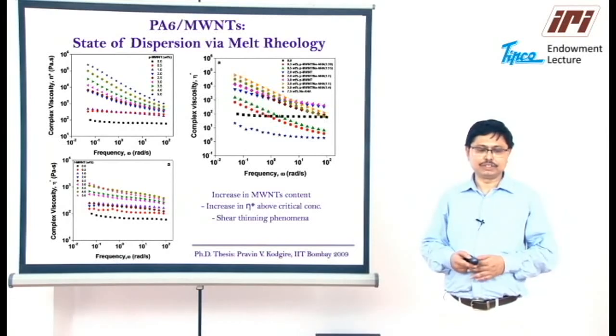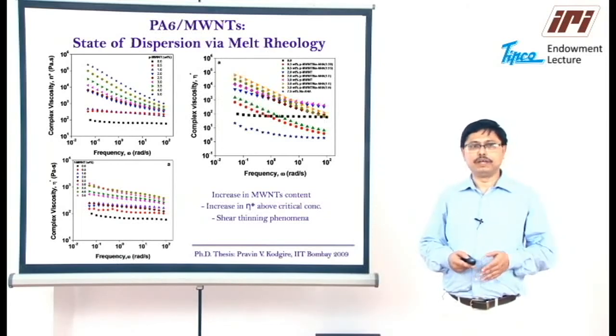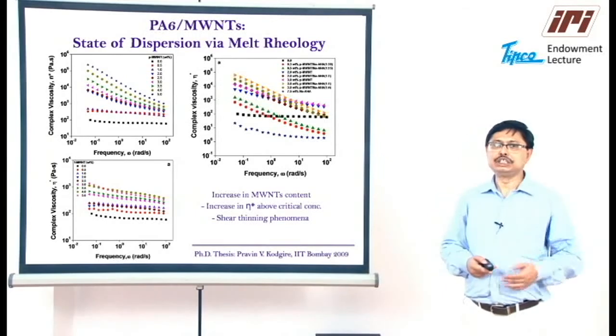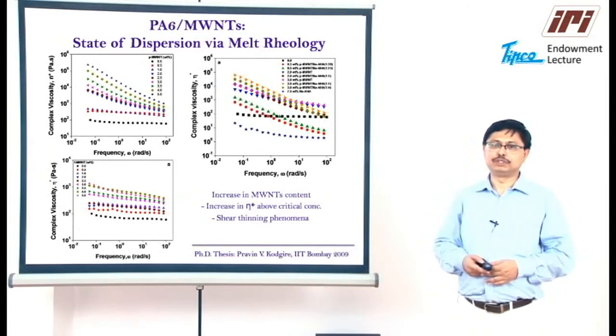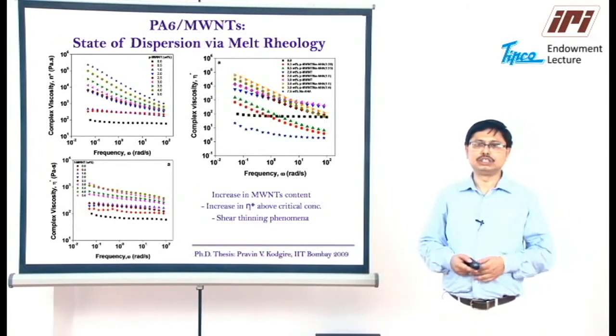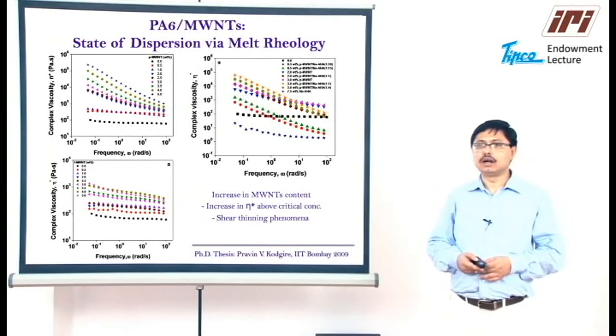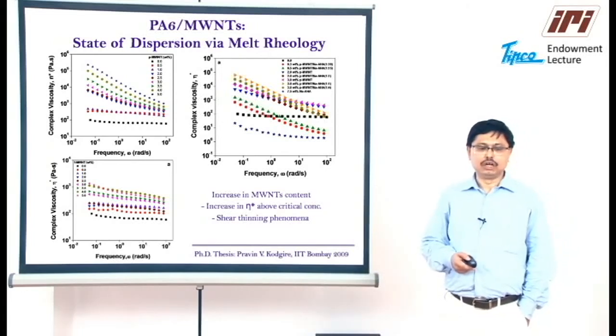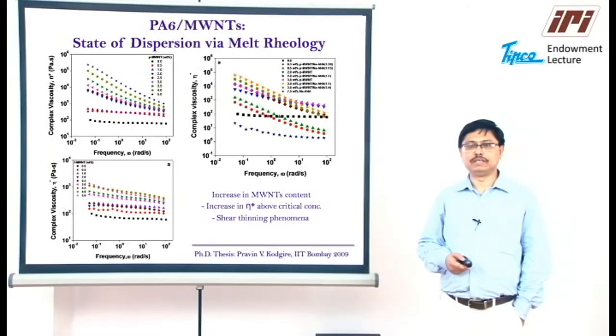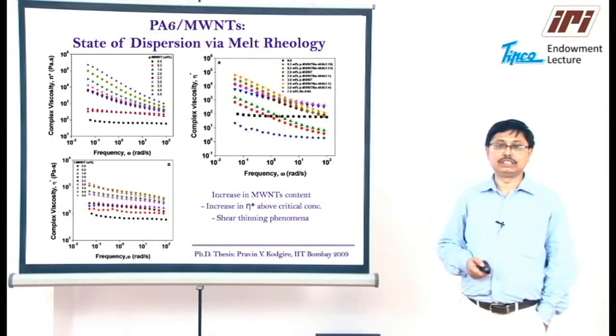In the complex viscosity versus frequency plot, there is always an increase in the low frequency behavior at a concentration between 2 to 3%, whereas in the case of NaHA modified multi-wall carbon nanotube material, we observe that even with 0.5% multi-wall carbon nanotubes, the slope of the curve of complex viscosity versus frequency increases as compared to the 0.5% based composites of either purified or functionalized materials.